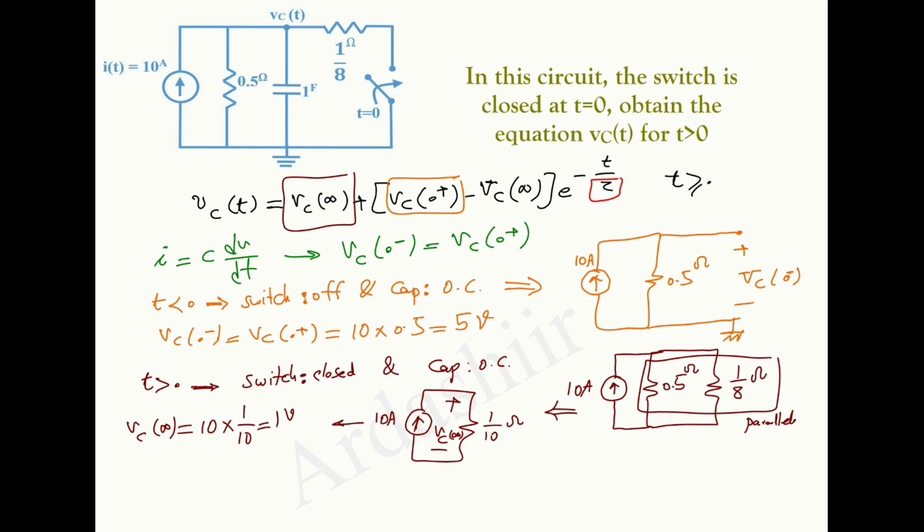The time constant of a first order circuit is also determined, and for this we need to determine the R equivalent after t equals 0, and tau is equal for RC circuits to R times C. R equivalent times C equivalent for after t equals 0.